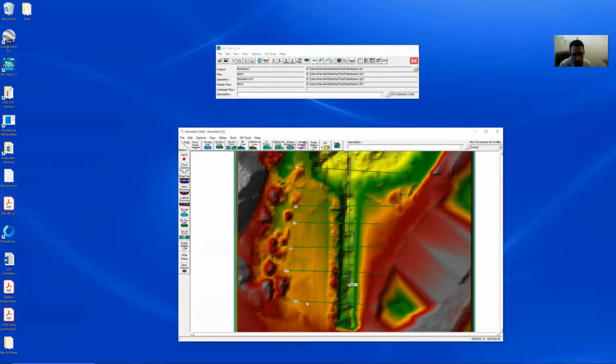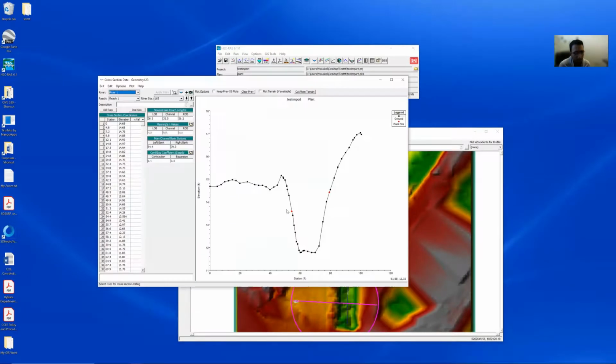So cross-section wise, we don't have it, right? We never introduced that in the RAS Mapper. You could draw a polygon for different areas. You have concrete, asphalt, shrub, whatever, and assign that number to automate that process also. But here, we want to just type it. There is no need to do a varied cross-section like that. With 3 numbers it is okay.